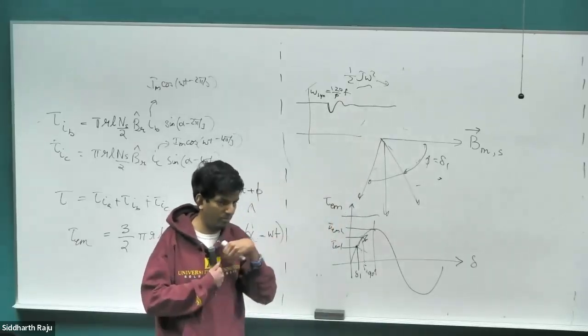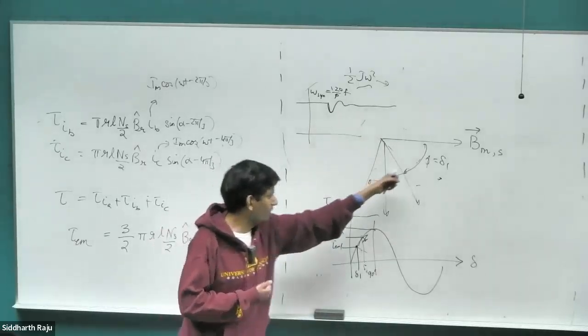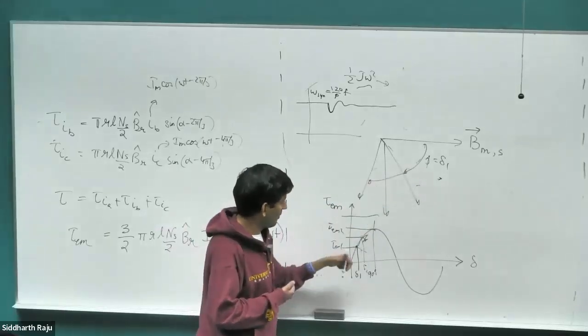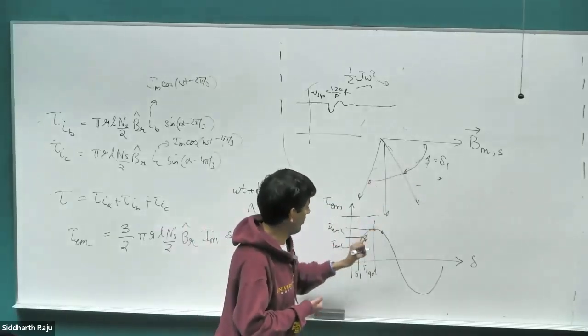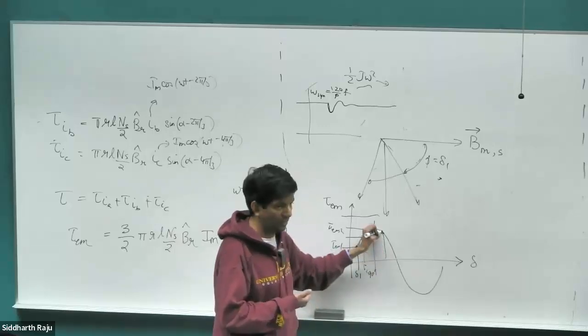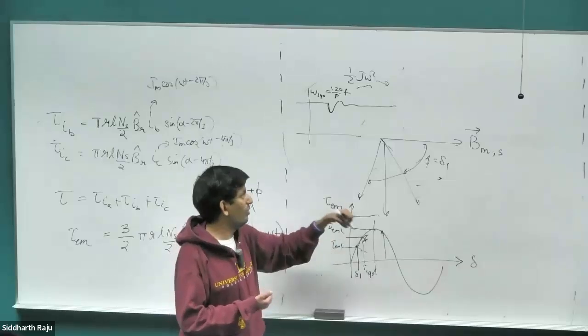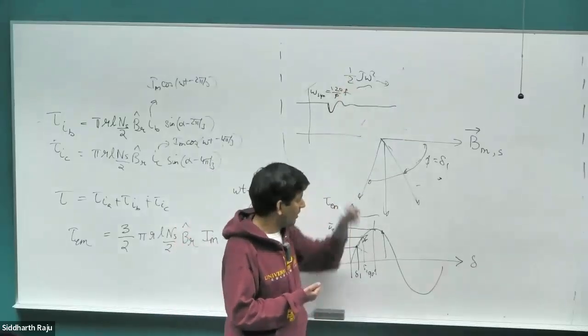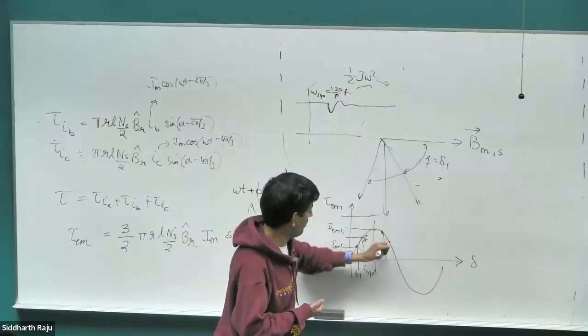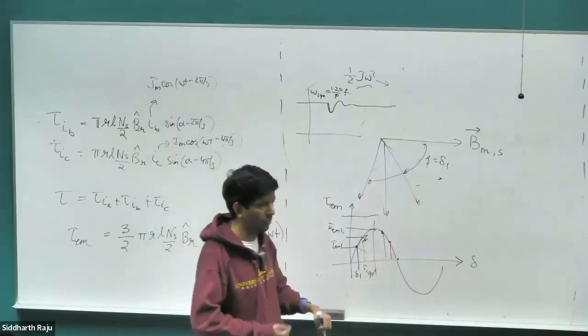Motor is slowing down. Separation between you and your friend is increasing. Right? So the delta angle keeps on increasing. But the problem is on the other side, the feedback loop is negative. When the delta angle is increased, then you're producing less torque than what the load needs. That means you're going to take out more energy from the inertia. That means you'll lag even further. You'll go further down until you come to a full stop.